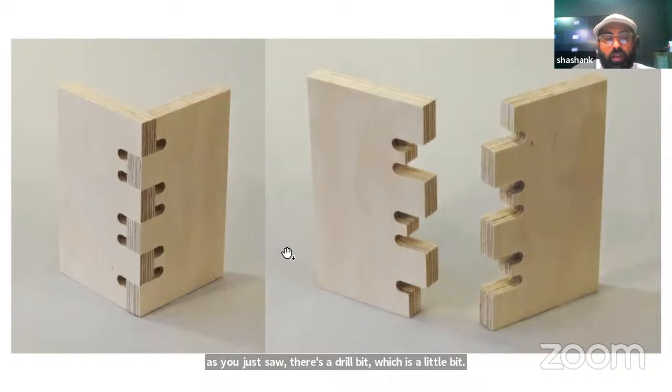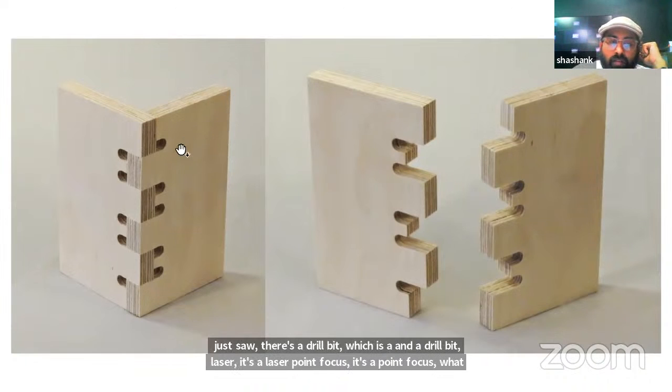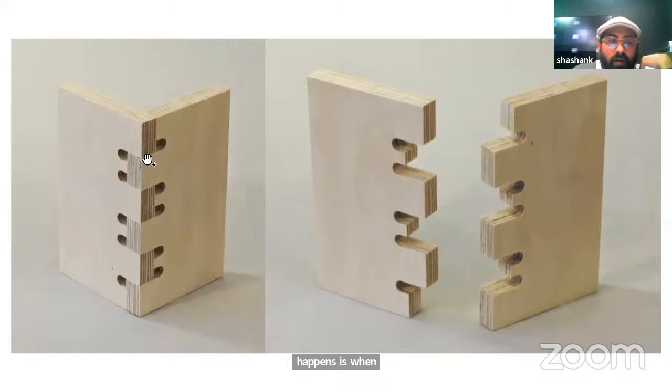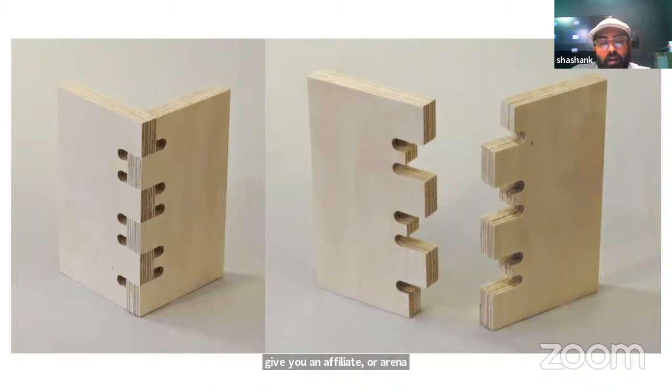When it's cutting, it will cut 90 degrees always. The problem with CNC routing, because it's a drill bit, is that it will not give you a 90-degree cutout. It will always give you a fillet or a radius of the particular tool. So if I'm using a 6 mm drill bit, I'll get a 3 mm fillet, which is not great.